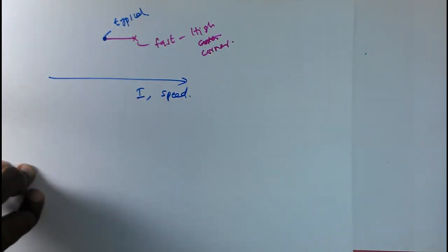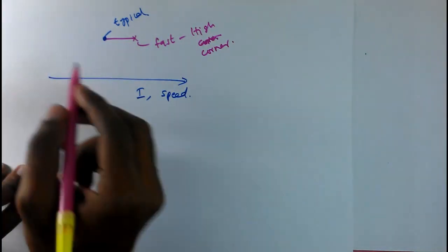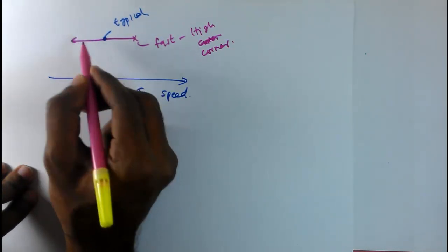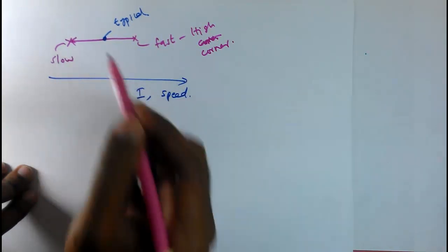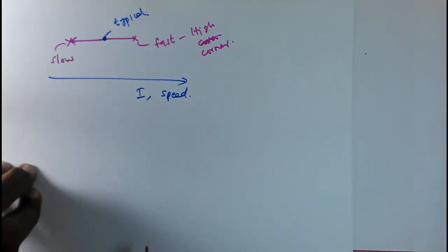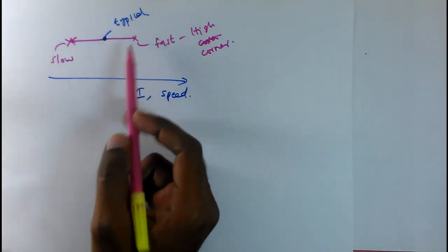Like that, VT can increase and the μ COX W by L term can decrease also. That means all the process variation is occurring in such a way that the speed of the MOSFET is decreasing or the current through the MOSFET is decreasing. In that case, it can go down to some minimum value. That is the other corner. This is the slow corner. So every MOSFET will be in between this slow corner and this fast corner.